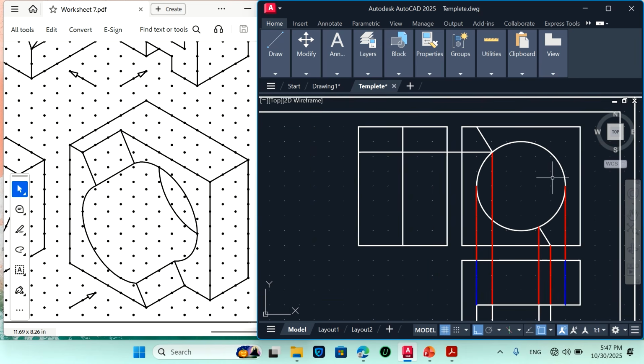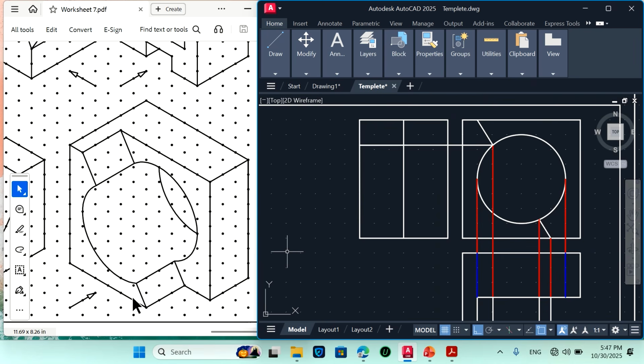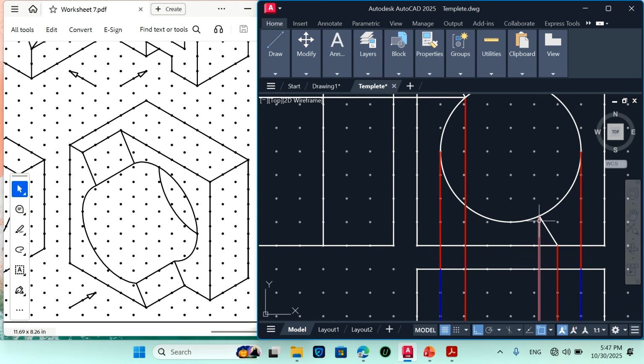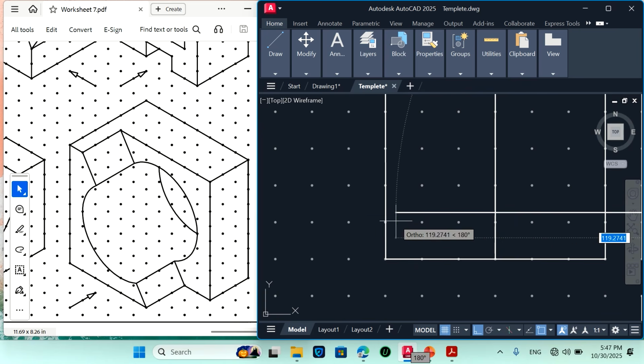So here if you see the corner points of the hidden line, the hidden to this inclined surface corner point, these two are coinciding with this, and these two lines, these 2 points are coinciding somewhere, and I need to draw the projection. So if I draw the projection from here, it will be coming somewhere here like this. So these are the other two corner points, which indicates that this is the curved surface.